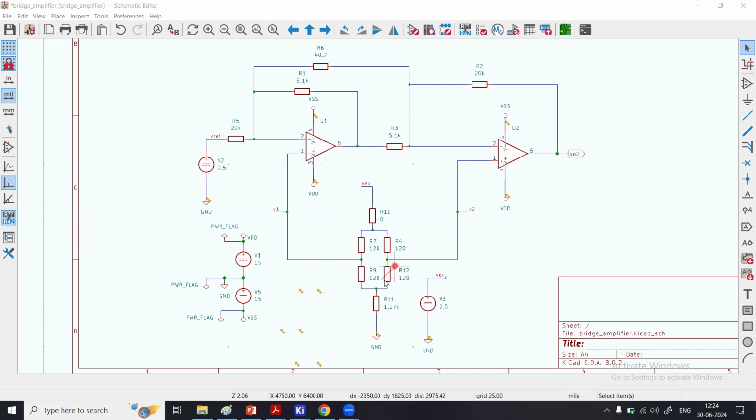But when there is a change in resistance of the strain gauge sensor, because somebody applied an external force upon it, the bridge is unbalanced. It goes from the initially balanced condition to the unbalanced mode, creating a voltage difference at these two junctions, which are again going to the respective positive pins. So V1 and V2, or V1 minus V2, is applied here at the positive pins, and accordingly your output will also vary. So a change in resistance is being converted into an equivalent change in voltage, and the change in resistance is happening due to the input, that is a physical quantity of force.